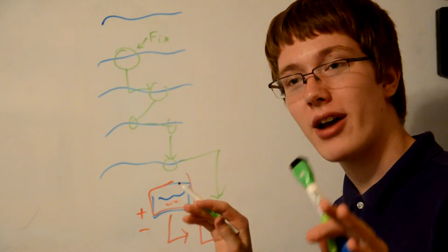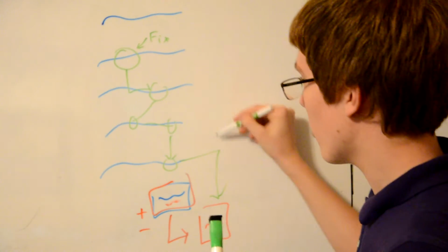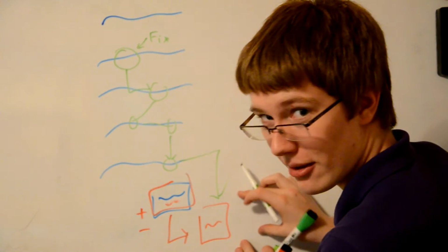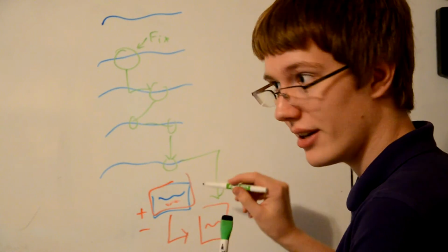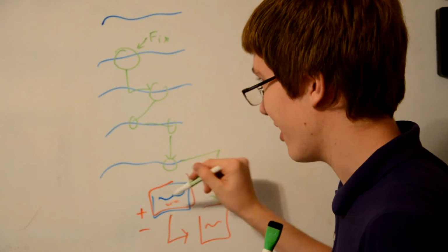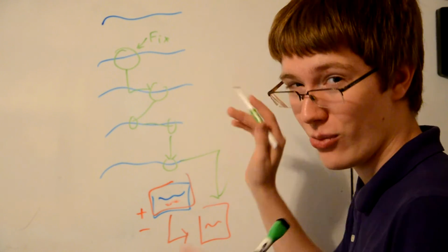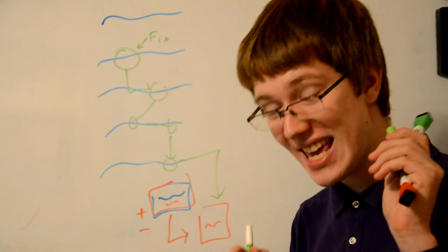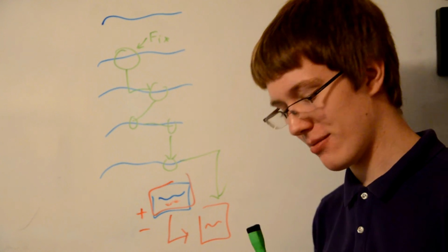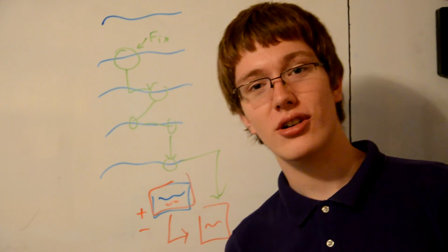With parametric modeling, we can make an earlier revision, and it carries forward all the changes to affect the final. With direct modeling, we can only affect the final thing we have. We can't touch any of this with direct modeling, but we can with parametric modeling. There's history with parametric modeling. And so we'll go ahead and illustrate this on the computer as well.